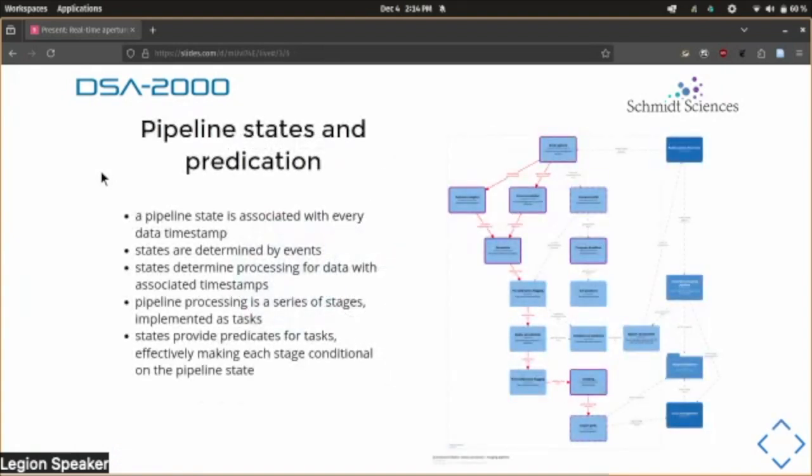On the right, it's too small to read, but that's a general flow of the pipeline we have. It's starting up in the very corner. That's the radio camera front end. The data goes through data capture, cross correlation, normalization, flagging, calibration, gridding, which is the computational high point, and then there's an FFT, and then you're done with the radio camera processor. It gets passed to the post-processing system.